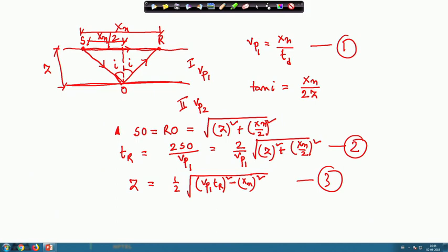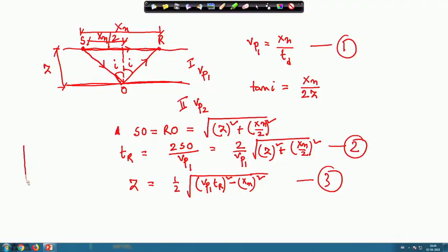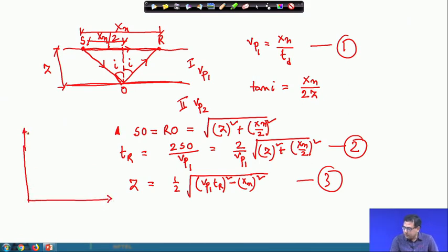Now, if we use the n number of geophones, then in that case if I draw a particular graph, that graph will represent x n and the t. T may be direct, T may be reflected. So, this is the 0 0 and x n will indicate the position of each geophone. So, this is the R1, this may be the R2, this may be the R3, this may be the R4. So, in this figure I have shown that there is a number of geophones we are placing with certain interval.